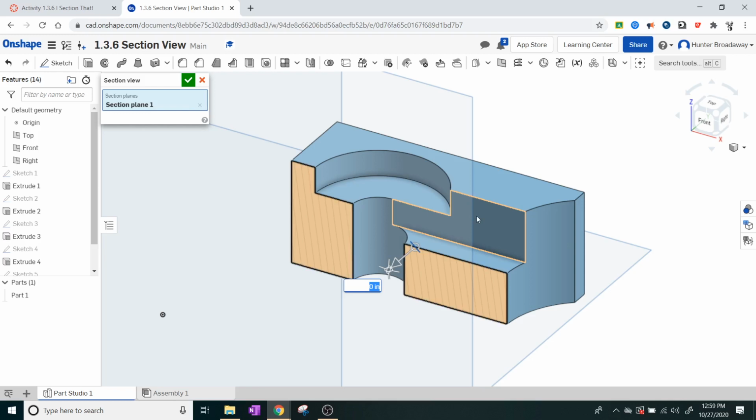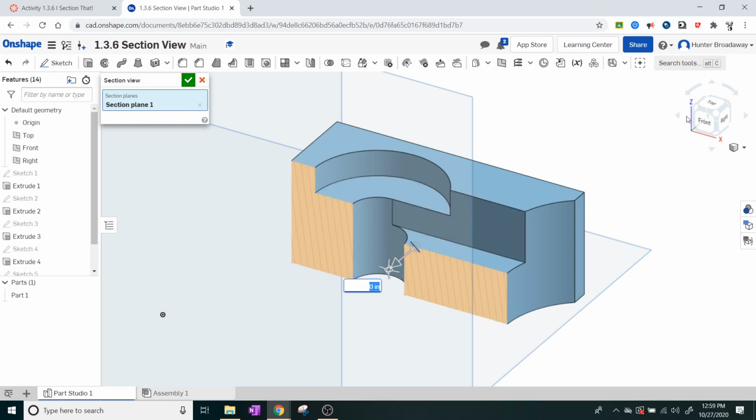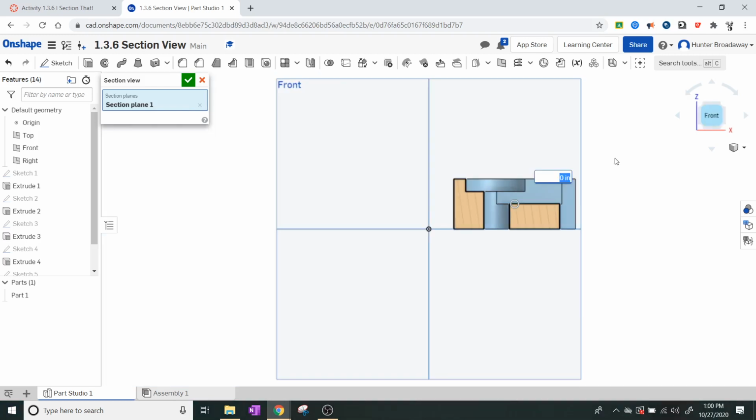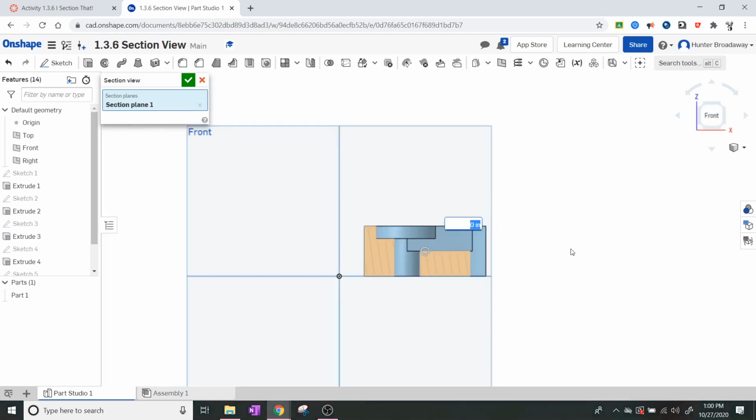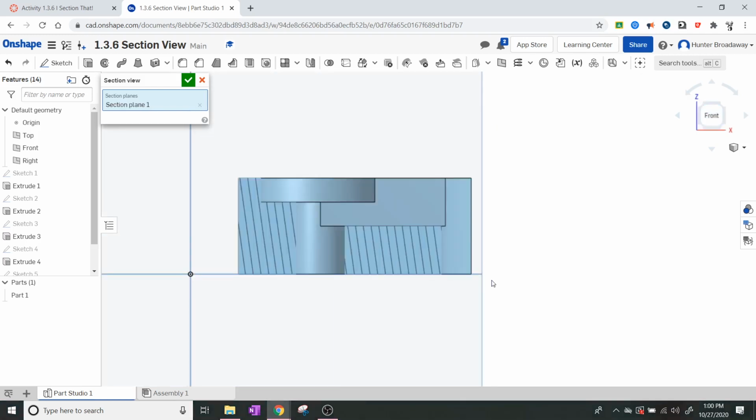So we don't need to make section lines everywhere when we make our sketch. It's going to need to look more like this, where we have our section lines right here in the colored in area. The other places are going to be object lines. I should have object lines over here. I shouldn't have section lines all the way through this stuff.